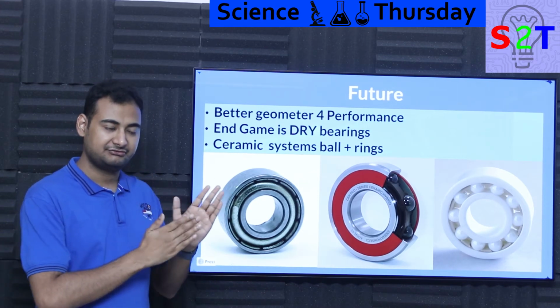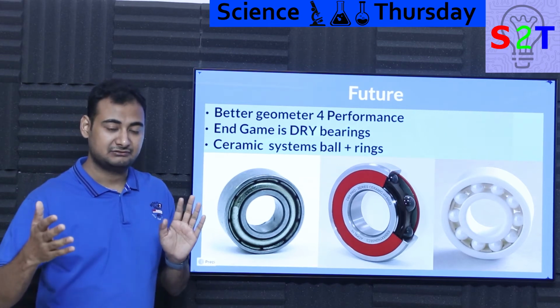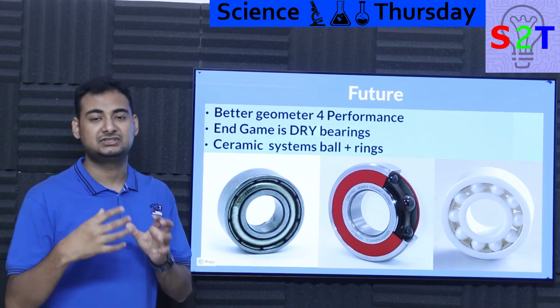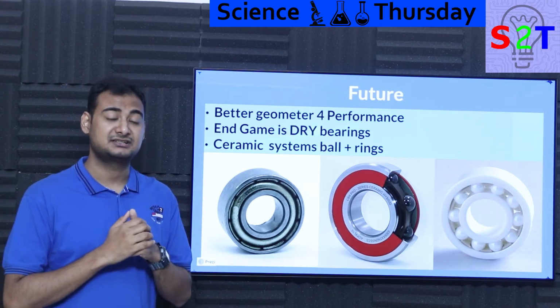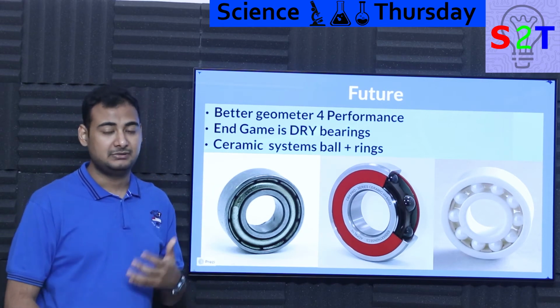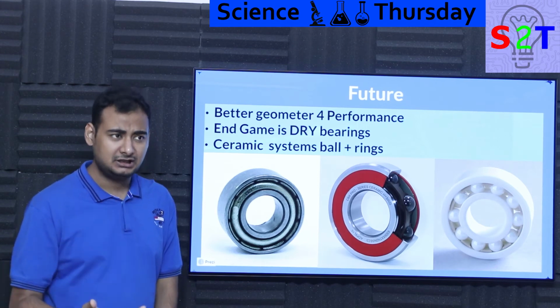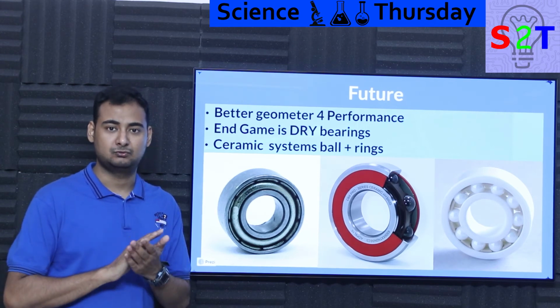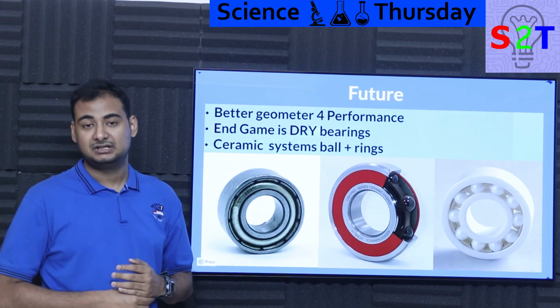Now the difference between perfect and absolutely perfect, or as perfect as we can make it, there is a giant amount of time, machining, and tools you have to spend just to make it a bit more perfect. Making it a bit more perfect translates to a lot of improvement. You can easily find bearings of the same size made by multiple manufacturers, and one would be barely good enough, another would be good with some long life, another would be like, whoa, this is butter. And even though the dimensions could be the same, geometry is a very critical factor.